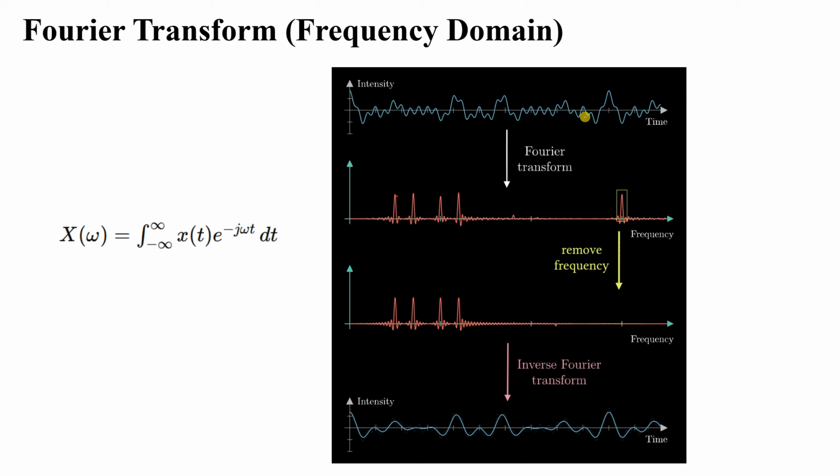Now you will see that the noise has a very large frequency, as you can see here, with a large amplitude. This one is our noise present in the recording. So what I'm going to do, I will look at what is the frequency of this signal, and then I'm going to design a filter that kills this particular frequency from this audio.